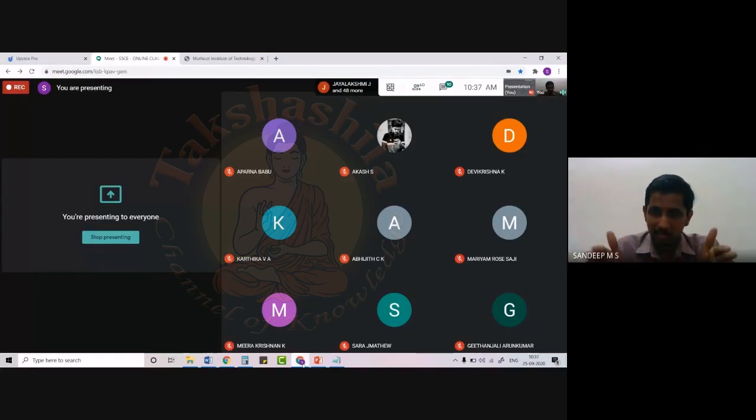That is, stirrups must be close enough to resist the shear force coming at this location. Once you increase the spacing, it is like decreasing the amount of shear reinforcement, so the section may fail. In such a case, in view of safety, you can round it down, maybe to 130 or maybe to 120. That is also okay. But you have to perform the check for minimum spacing and maximum spacing.